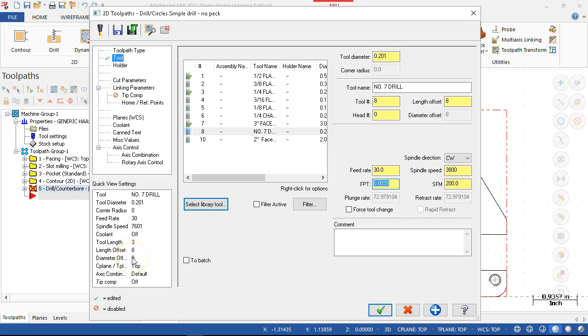Graham, this seems like a little bit late in the semester to ask this question. Surface feet per minute is the parameter that you want to begin with, and it suggests feet per minute and your speed, and then you go in and manually say, yeah, but let's tune it in a little better. Right. So we're starting with that chart that said aluminum can run at 200 surface feet per minute, steel at 100. Exactly. So we're starting with that.